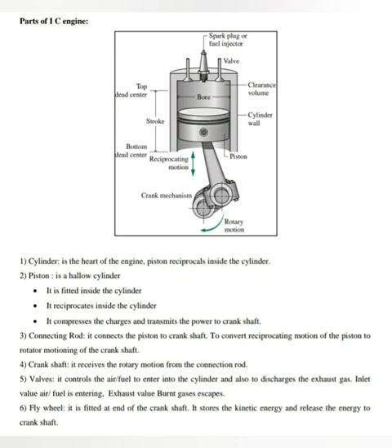The next part is valves. There are two valves for each cylinder, the inlet valve and the exhaust valve, which is also called the outlet valve. Fresh charge or fuel mixture enters the engine cylinder through the inlet valve, while the burnt gases are discharged outside the cylinder through the exhaust valve. Both the valves are opened and closed by means of cams driven by the camshaft through a timing gear or chain, so that the charge enters or discharges the cylinder at the right time.